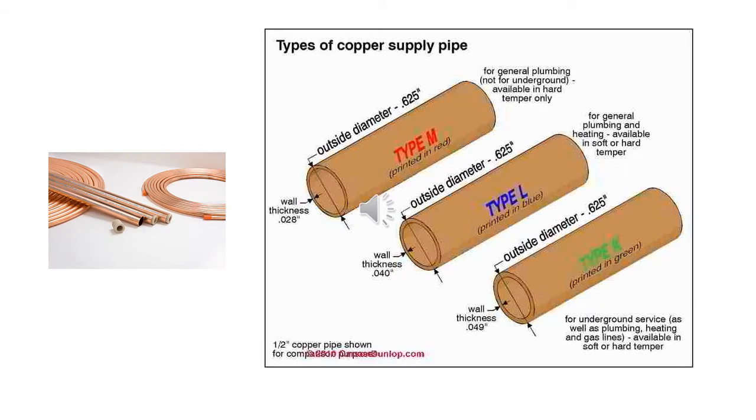Copper pipe for the plumbing, heating, and air conditioning industries is available in drawn and annealed tempers, and in a wide range of diameters and wall thicknesses. Temper describes the strength and hardness of the tube. In the trades, drawn temper tube is often referred to as hard drawn, and annealed as soft copper tube. Hard drawn pipe comes in lengths, and soft copper tube comes in rolls. Hard drawn copper shouldn't be bent. Soft copper tube can be bent.